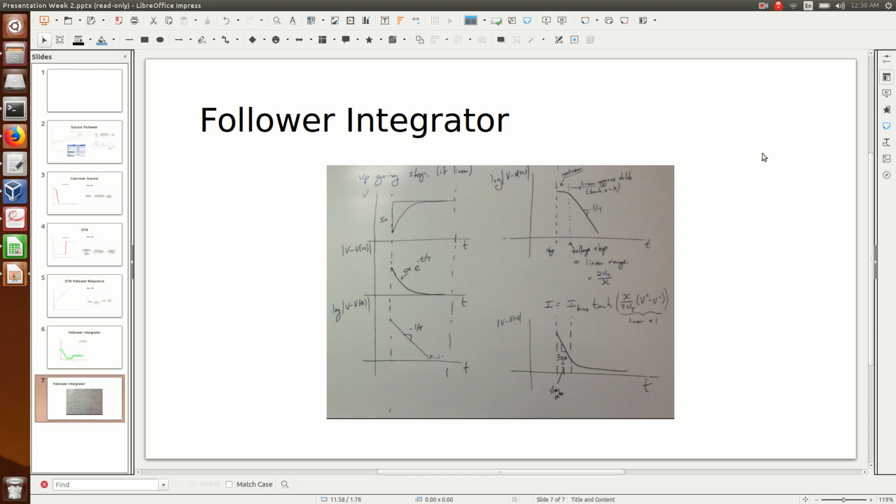So when V plus and V minus are roughly the same and delta V is close to 0, the tanh function essentially becomes linear with respect to delta V. So this gives a linear first order differential equation for the output voltage, which is what gives us this solution here, and which is what you see in this section of the graph here. But in this section, V plus and V minus are too far apart from each other to give that exponential result.